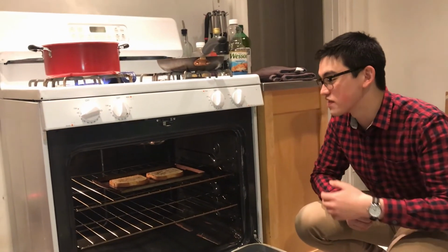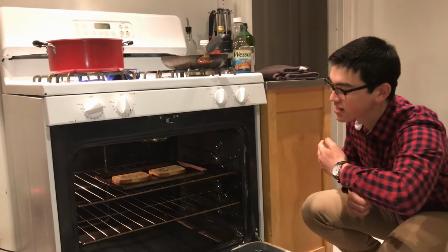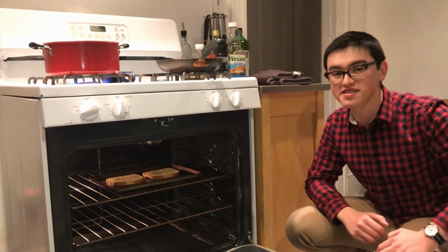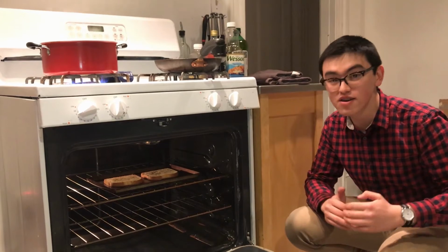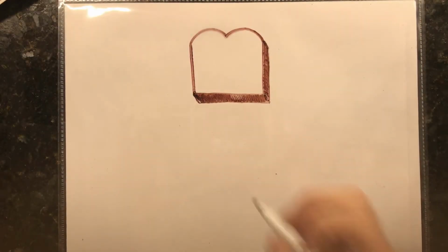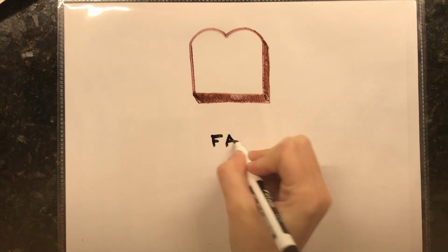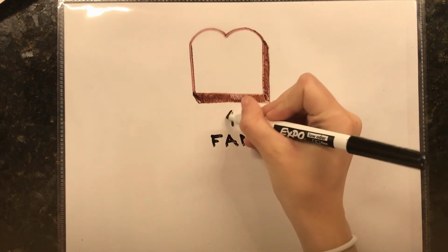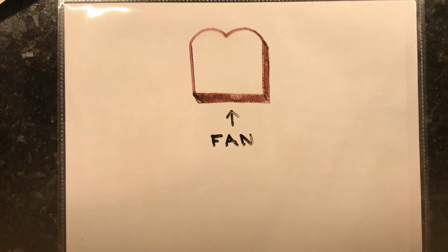So the air in your oven will be moving as part of forced convection, where it will blow from one side to the other. But there's also free convection, and that happens whenever air densities are different, or even fluid densities, like whenever you're boiling water. Forced convection occurs when an external force, in this case a fan, moves a fluid, in this case air, across the surface of an object.